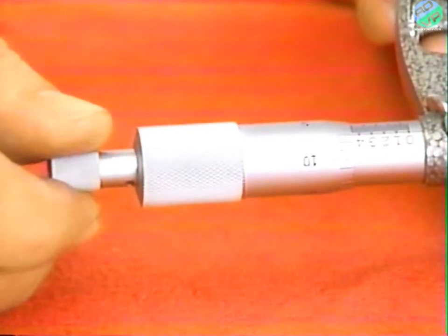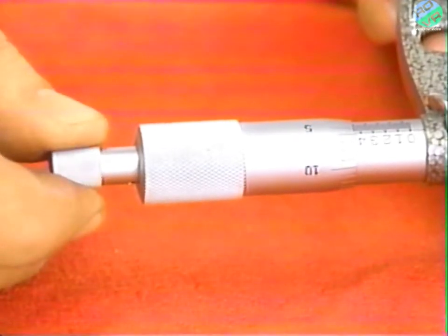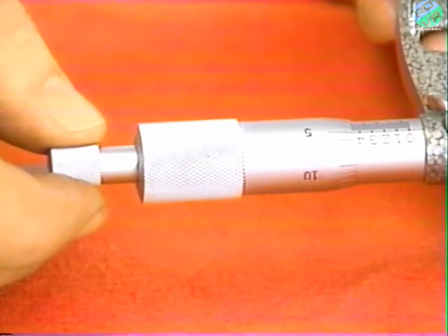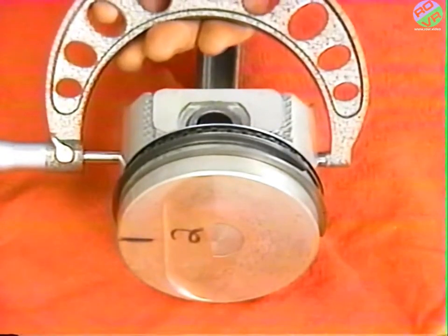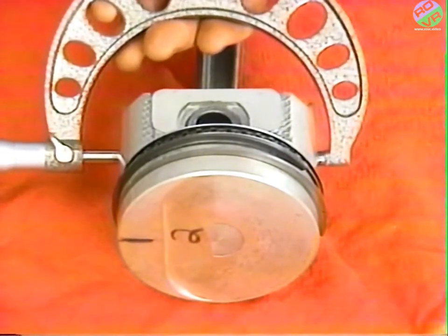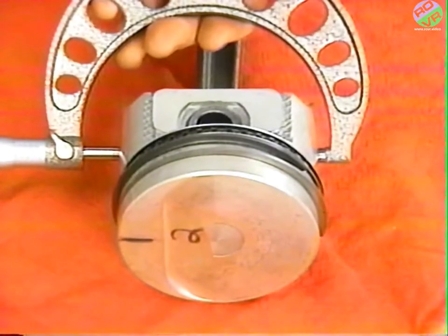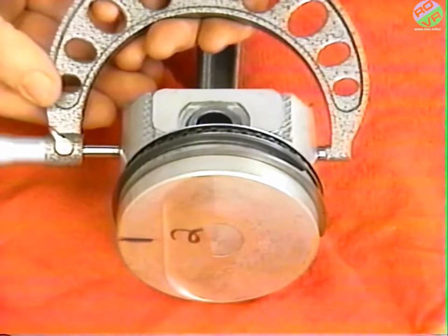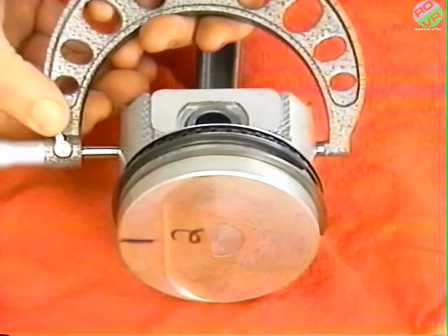If the micrometer has a ratchet at one end, use it. The ratchet prevents over-tightening, which can bend the frame, producing incorrect readings. The workpiece must slip through the micrometer with a very light force. When you're satisfied with the adjustment, read the micrometer setting, being careful not to move the adjustment. If the micrometer has a lock, use it to lock down the reading.